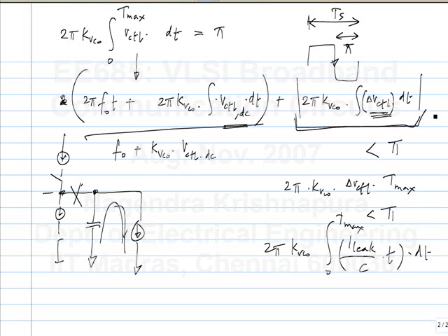Yeah, that's correct. That is why the data should be such that the number of consecutive identical digits is limited to some value. There will be a constraint on the data. If you have random data, the transition probability is half, right? So let's say you design this clock and data recovery circuit so that it tolerates 100 consecutive identical digits. What is the probability that it will actually drift away beyond that?